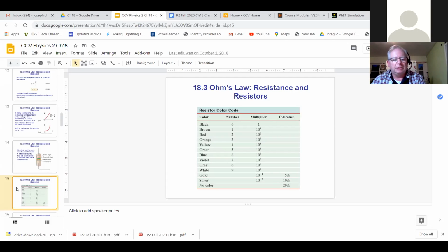So these resistors are really small, and I'll show you some in a second, but they're too small to actually write anything on. So by using color codes, we can translate this to whatever the value happens to be. So we need 10 digits altogether. So we use the colors black, brown, and then the colors of the rainbow, but that's still not enough. So we have to throw gray and white in there too. And between all of those, that gives us 10 digits.